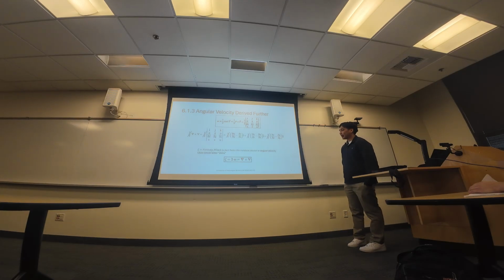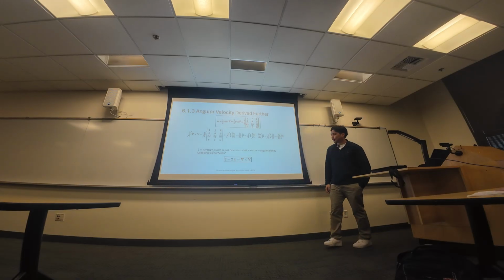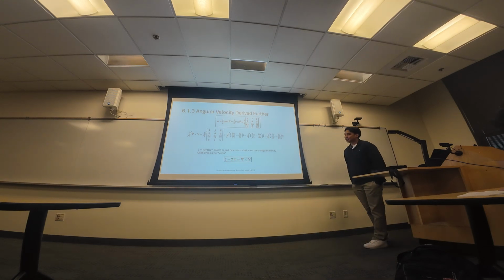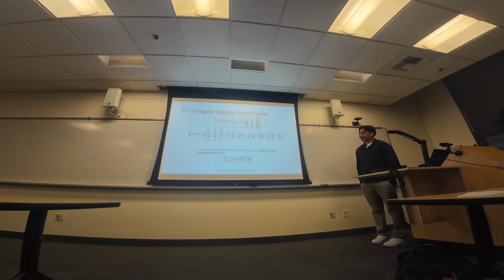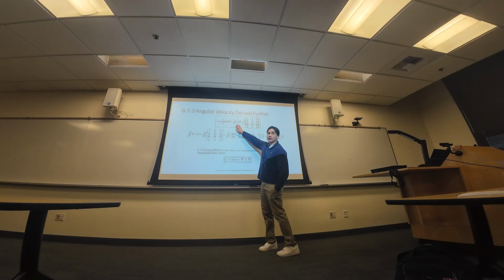So all of that being said, there is this term called vorticity, which essentially is just twice your angular velocity, omega. And they use the term zeta to define that. I always had trouble writing that one. It's a weird one to write for Greek letters. So you can see it's essentially your omega equation up here, but without the 1/2.